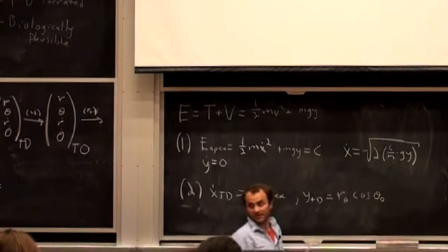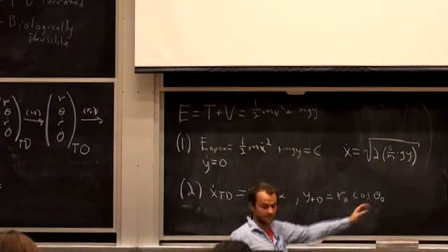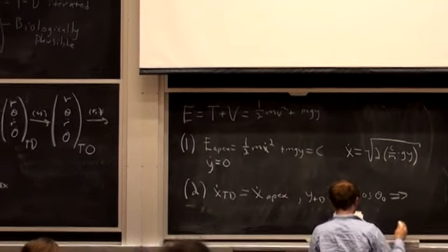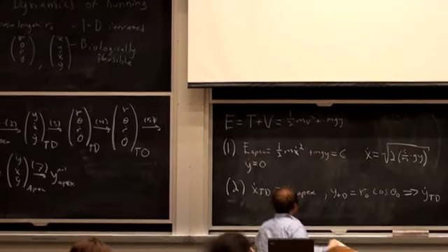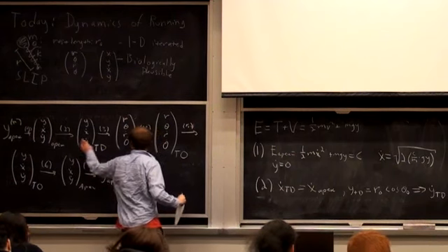So this is what I was talking about with the desired theta. Right? You know you're going to touch down at this desired theta. And since we know our energy, we can get y dot at touchdown. So here that gets our transition from apex to touchdown.